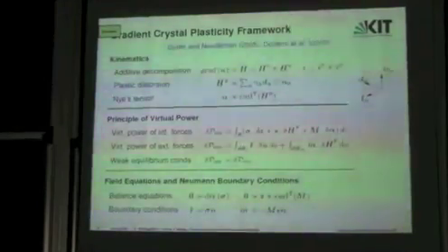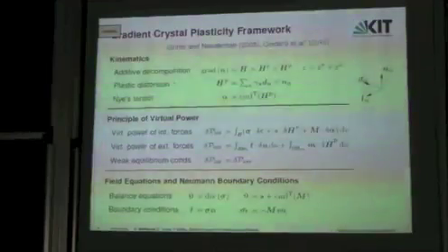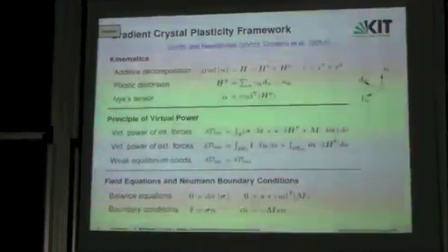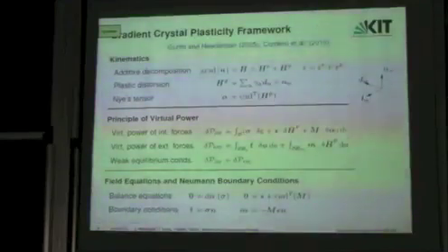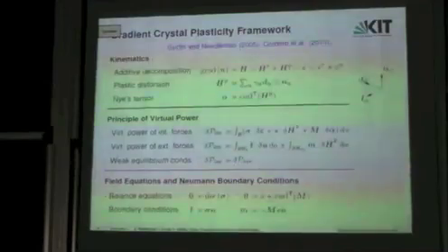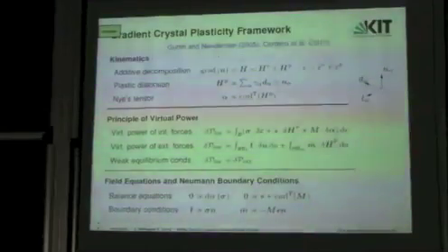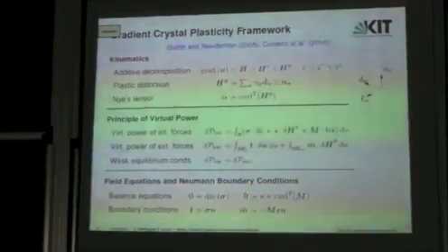However, it was then realized after some time that, like every model, this model has some limits, which appear when you go down with your specimen to the micro world. Like if you take, for example, a specimen which is only some micrometers large, then it turned out that using the classical theory based on these kinematics underestimates the strength of the material.